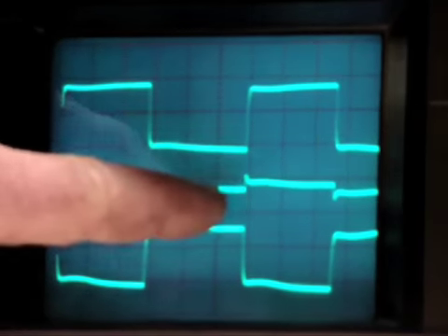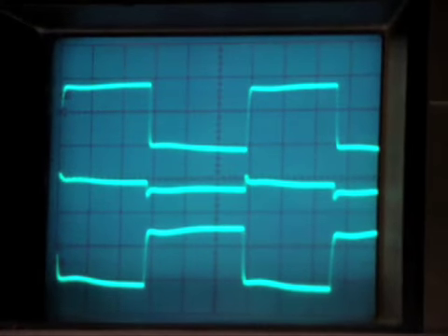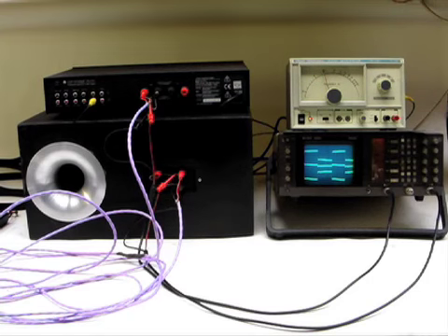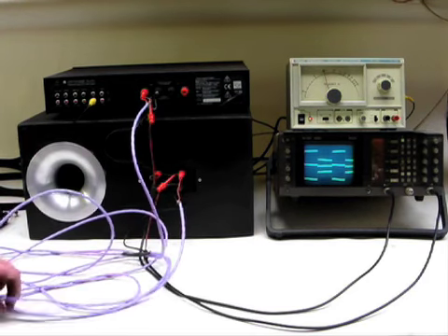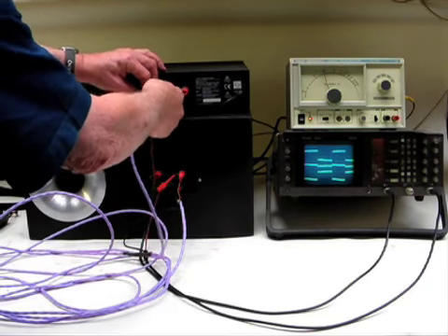And you can see this step here, that up down, that's due to the high DC resistance of this cable, and you can see the severe spike at the transient. And this is a cable with a characteristic impedance of about 150 ohms, but a relatively high DC resistance.